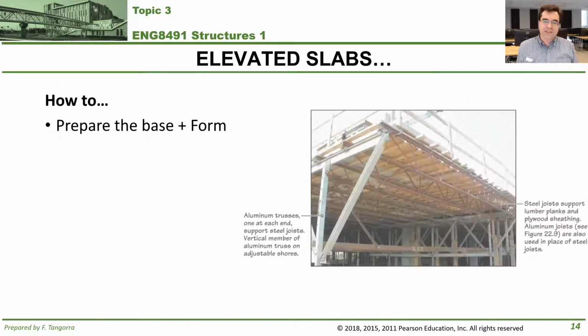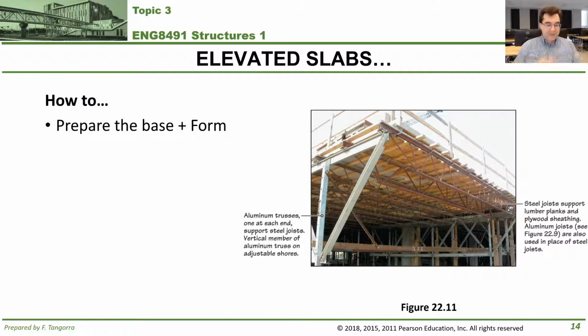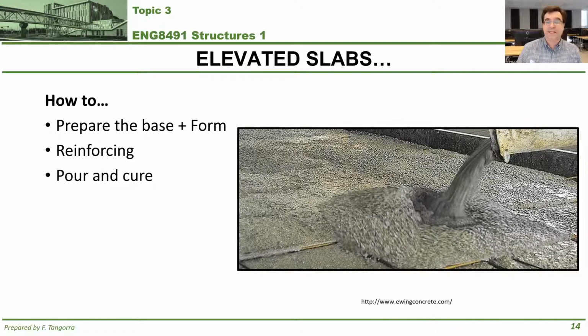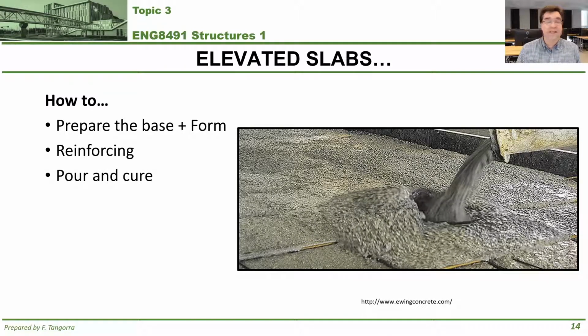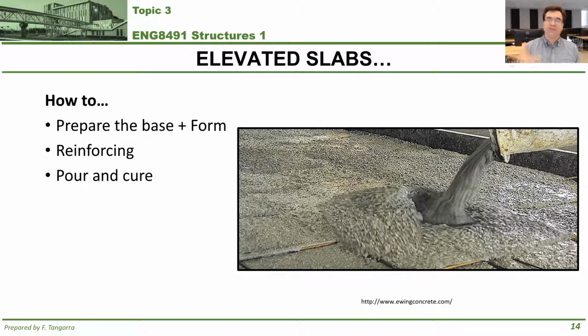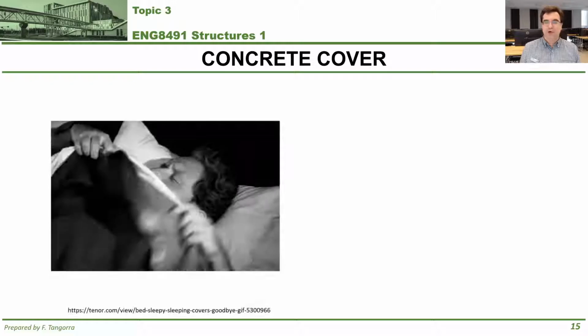Another possibility is that you build up that form, that flat base, custom, okay, for every application you're doing. Don't forget that again, for reinforced concrete, the forms typically are the expensive part for this, okay? Then you place the reinforcing, and that's in the parallel and perpendicular direction. Then you pour your concrete and let it cure so that it reaches the desired strength, right? It goes from fluid to solid, and you're good to go.